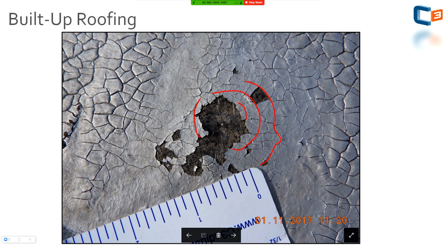What happens here a lot of times is engineers come up and target the alligatoring, is what a lot of people refer to it as, all this blistering on the surrounding flood coat. And they say, well, it's cracked there too. What's the difference? The difference is one is caused by an impact, and one is caused by just sun degradation. If you have an impact, it's generally spalling off that flood coat. It's bruising the material, and you have a concentric fracture extending from that point of impact. This is different from heat blistering, where you a lot of times have just linear, jagged, random distributions of cracks. It's very different. It's easy to determine the difference between the two.